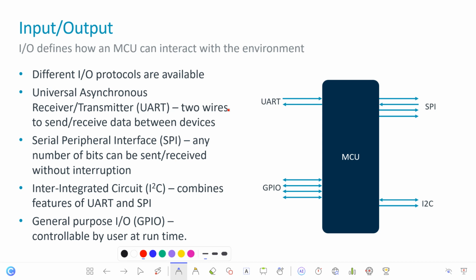All right, now these communication protocols range, when it comes to IoT, from serial TX and RX protocols such as the UART. Here I have TX and here I have RX, sender and receiver, that allow two devices to exchange data in the form of packets asynchronously using two wires at a speed called the baud rate. Here the speed can be a maximum of 115200 baud.